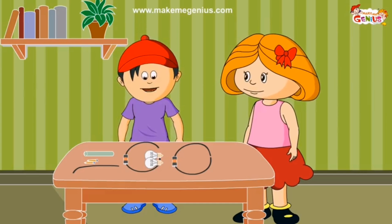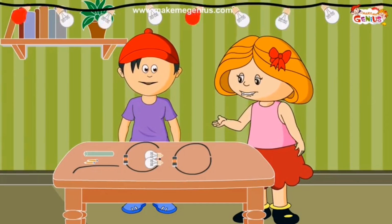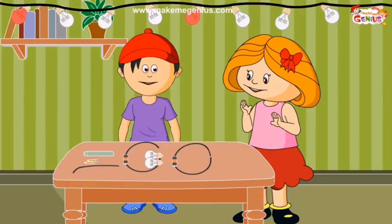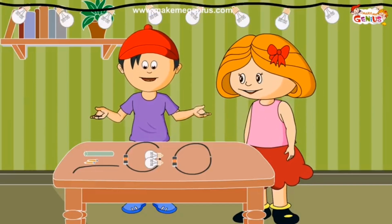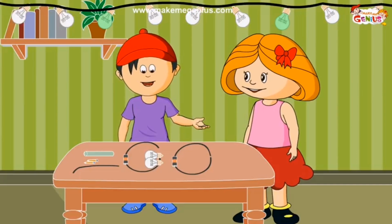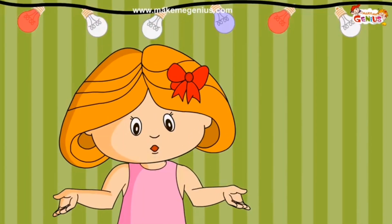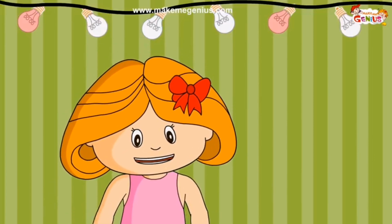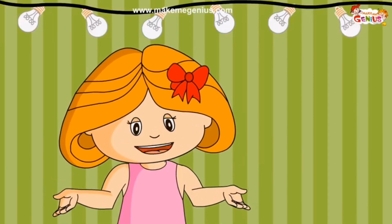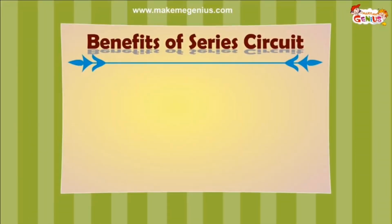Is there no use for this kind of circuit? We use this type of circuit in Christmas or Diwali lights. One small bulb after another. But if one of the bulbs goes off, all lights will go off. And yes, there is another disadvantage also. If you keep increasing the number of bulbs in this circuit, the light of each bulb will get dimmer than before. Are there any benefits from this kind of circuit?